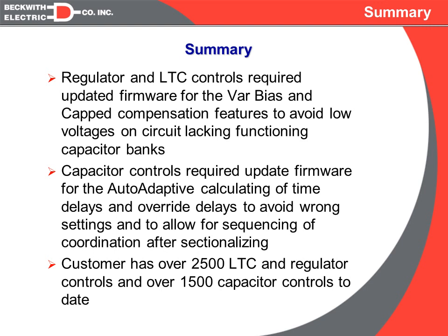We then had to address the coordination issues, and that was done in the capacitor controls by having the delta voltages become part of the calculations. And by doing so, we also solved the third problem, which was maintaining coordination of the system even when we were sectionalizing and tying circuits together and functionally moving capacitors from one circuit to another.